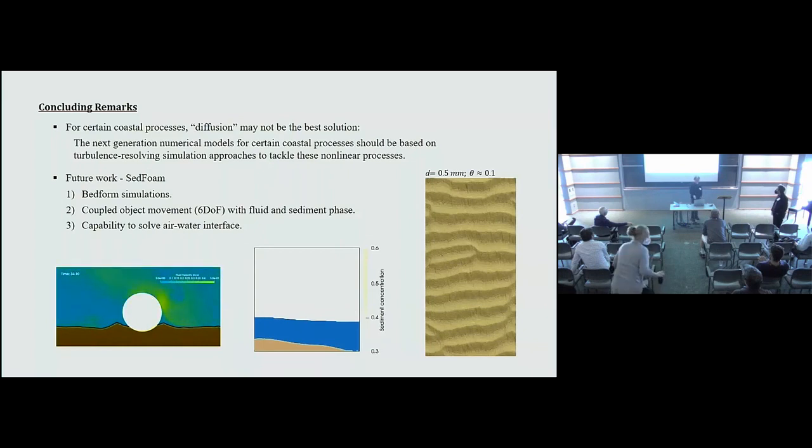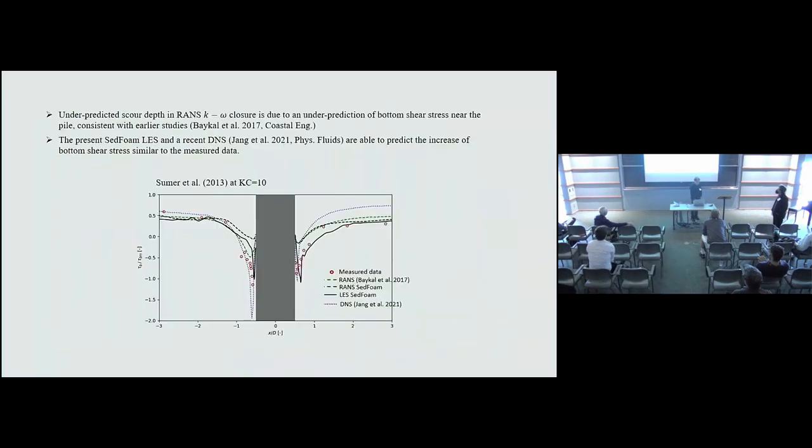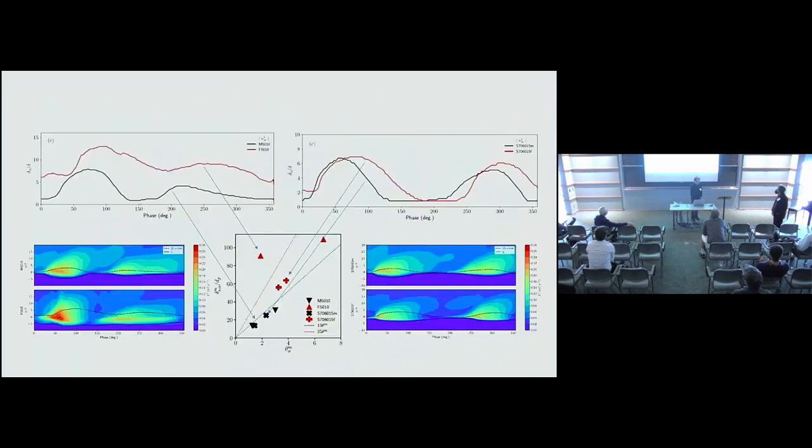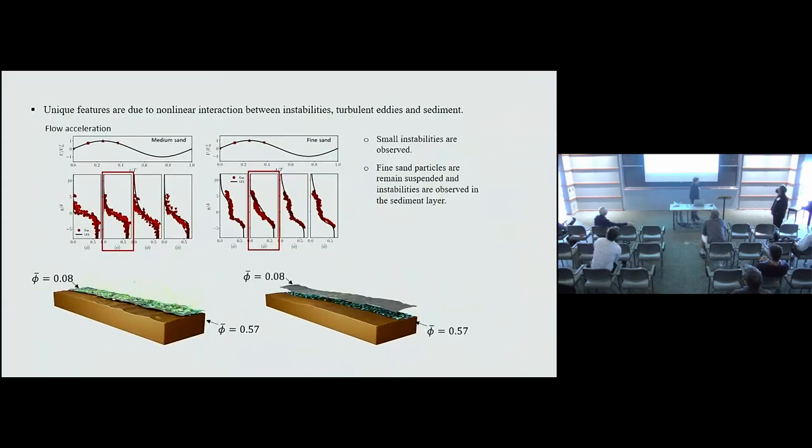Essentially, because of the two-phase approach in which we resolve turbulence, we also have, first I just want to point out the way we model the concentration profile. We can model the sediment concentration all the way from the settled bed to the very high concentration regime dominated by the contact load, to a lower concentration regime maybe dominated by mu-I rheology, kinetic theory. And then this part of the transport is really dominated by turbulence, turbulence suspension. So they are all one single system, and I think that's the advantage of using a two-phase model. It's just that we don't resolve the grain interaction.